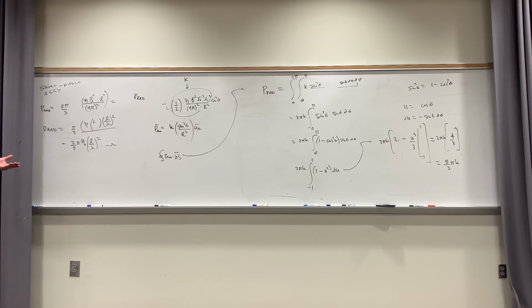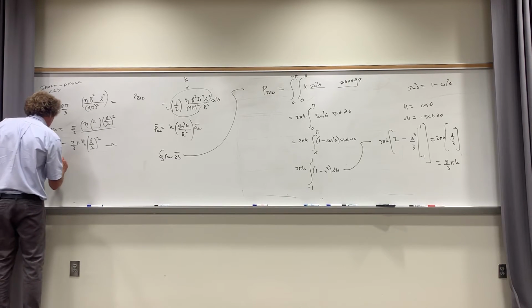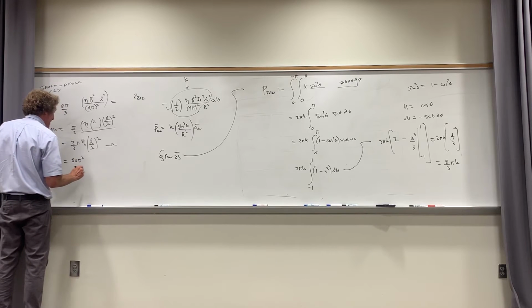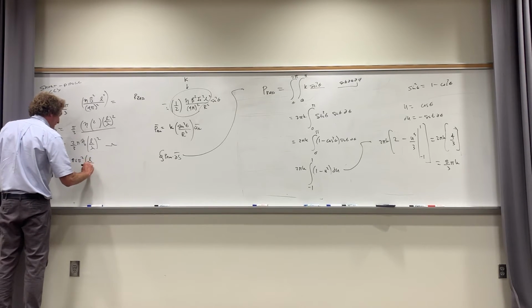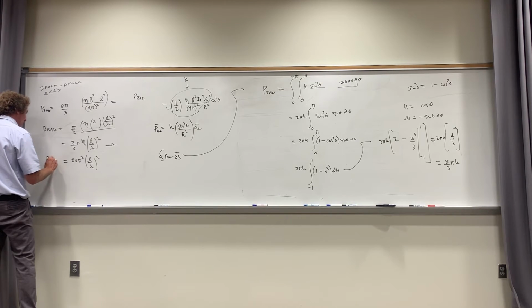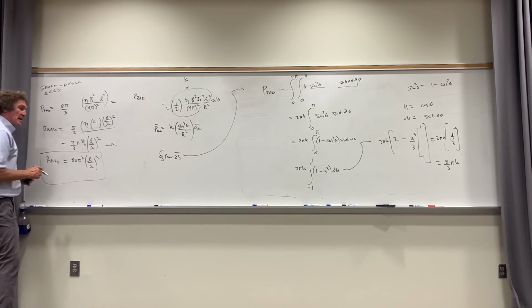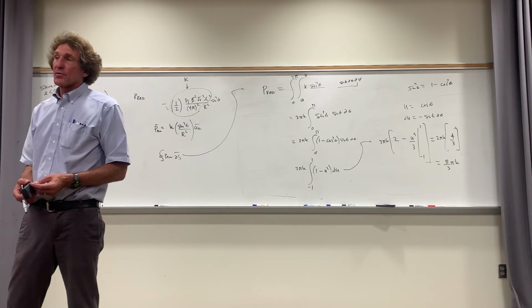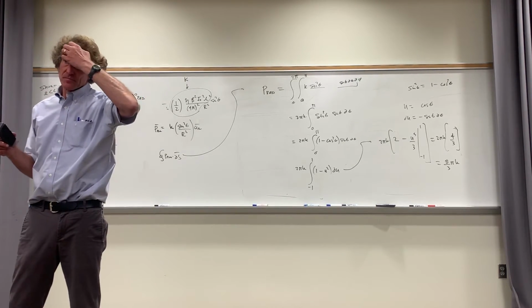Yeah, all right, but you can do that if you want. You can put this as 80 pi squared, I guess. 80 pi squared, and this is going to be times L over lambda squared. Yeah. And that's R rad. Now, that's kind of important to know. That's the radiation resistance, and it's effectively the resistance due to the creation of power that's launched.